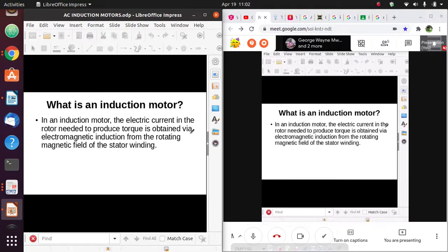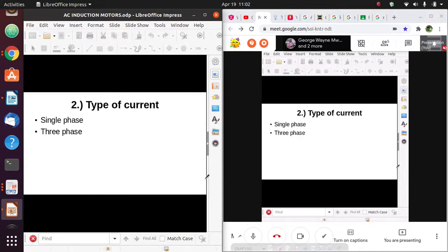So the magnetic field of the rotor and the magnetic field of the stator link, flux linkage. Once they link, they will be rotating in the same direction. The rotation of the rotor will follow the direction of the rotation of the magnetic field produced by the stator. So that is the basic principle of how an induction motor works.